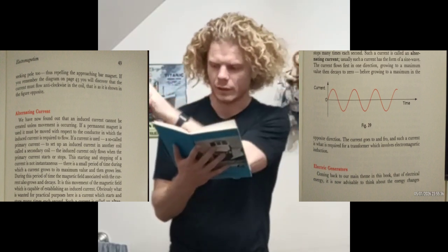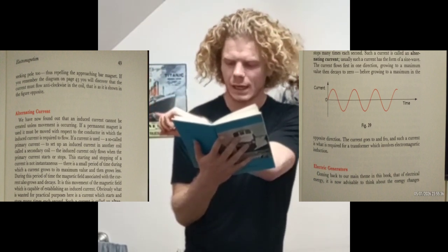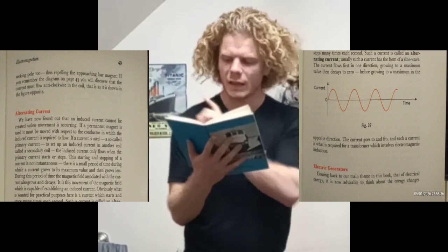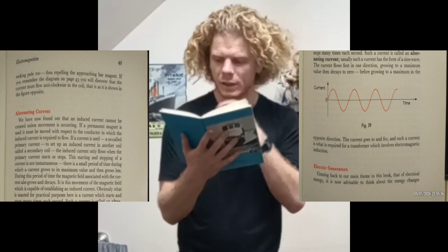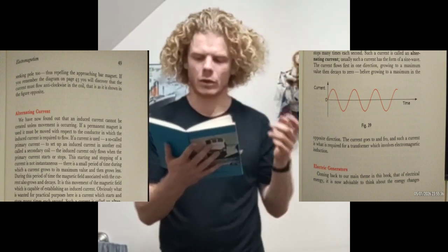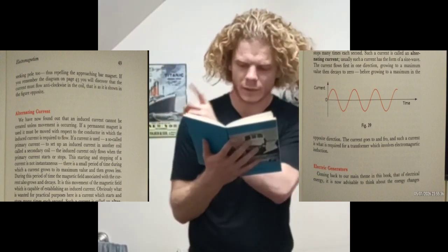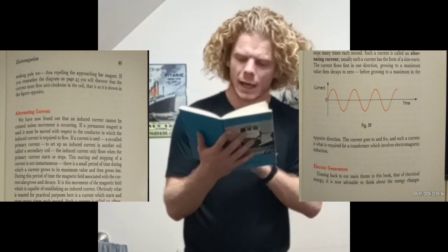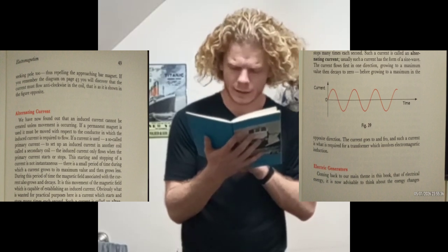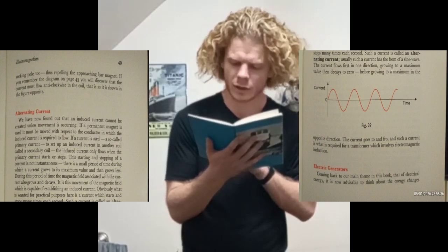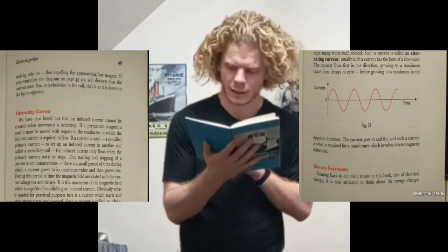The meter shows a deflection, say to the right. Once the current is steady in coil A, no current flows in B. The meter shows this by returning to the zero reading. When the switch is opened again, thus stopping the current flowing in coil A, again there will be observed a pulse of current in coil B, this time moving the meter to the left. The currents caused to flow in coil B are called induced currents, and the phenomenon itself is called electromagnetic induction. This occurs whenever the current starts or stops.